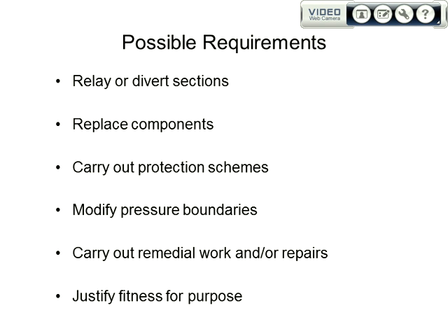So this is the standard list that you would apply. The majority of these issues, the first issues, will apply if you're changing the pressure and if you're changing the safety level of the pipeline. If you're going to change the maximum allowable operating pressure, you're going to have to change the pressure boundaries, so you're going to have to look at that.